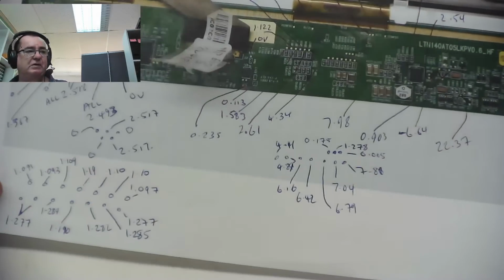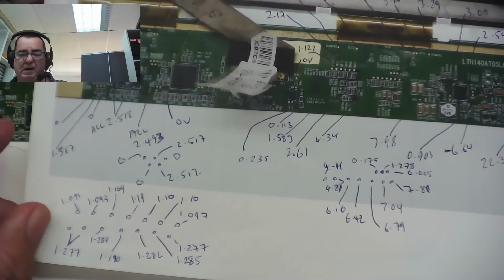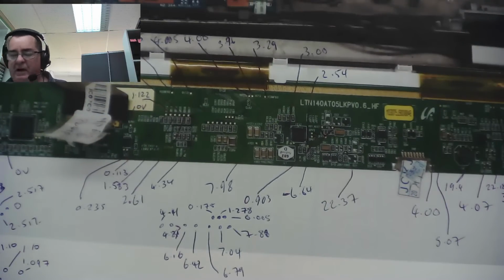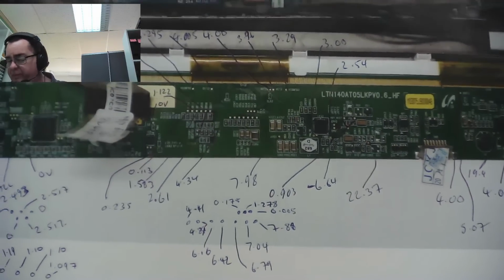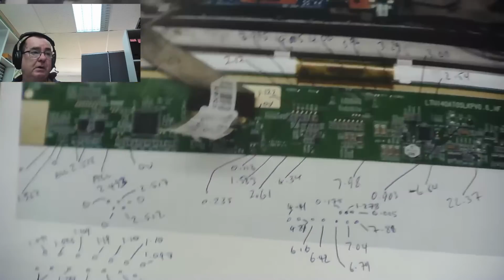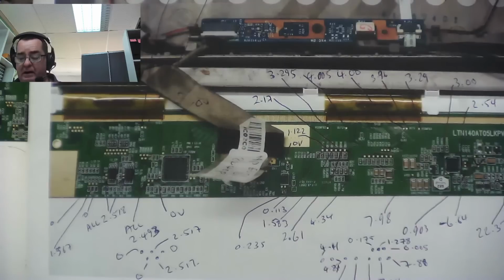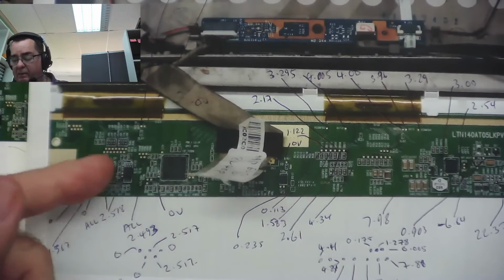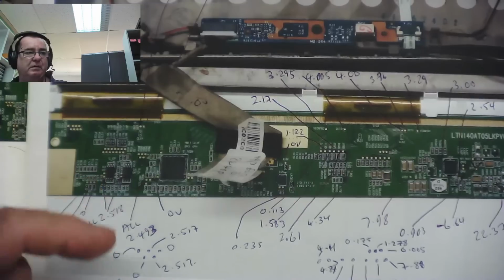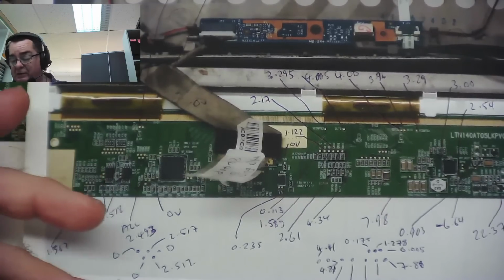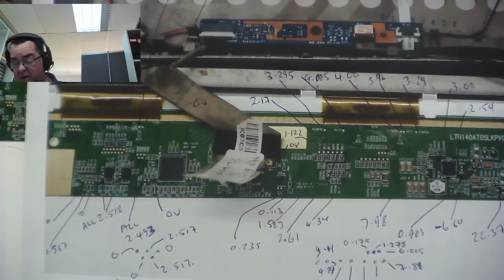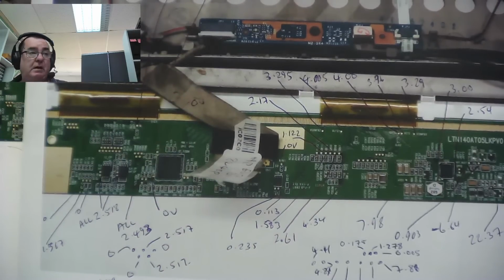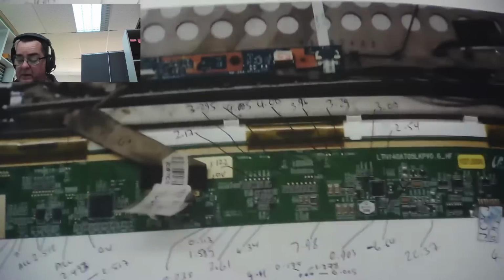You know, there wasn't a case where on one board I got 12 volts, the other one I got like 2 or half a volt. There was nothing glaringly different. They weren't exactly the same, but they were all close enough, I think. And that didn't help us. We then checked this video chip, and we could see there was video going to the screen. We discovered these EPROMs are to do with recognising the screen, and the laptop does recognise the screen, but we changed the video chip, we changed the EPROMs, and we still have this grey screen, backlights and no picture.